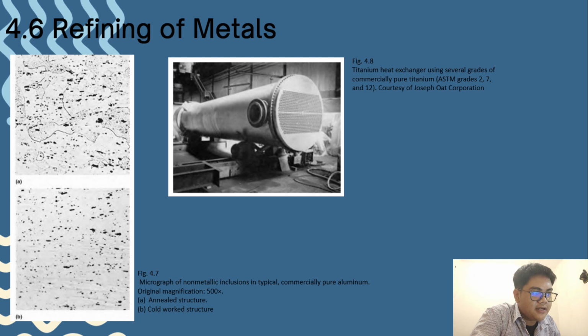Gold refining is the relatively simple process of heating the gold to a very elevated temperature. At this high temperature, most of the impurities in the gold react with oxygen in the air to form metal oxides. Some of the oxides formed by such reactions are gaseous and therefore carried away by the surrounding air. Other oxides are not gaseous, but the reactions to form these oxides produce relatively low density compounds that float on molten gold as a slag or dross.